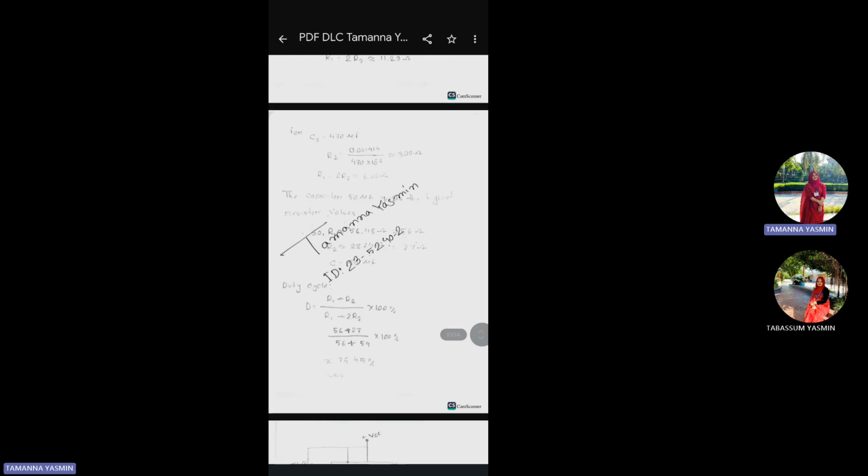Using the standard astable mode formula for the 555 timer, I calculated the combined resistance value used to achieve 255 hertz with the capacitor. Then, using the duty cycle formula, I set up two equations to solve for two resistors, R1 and R2.